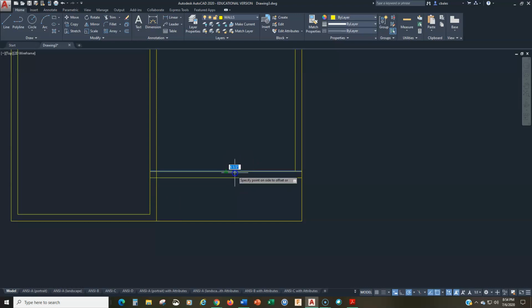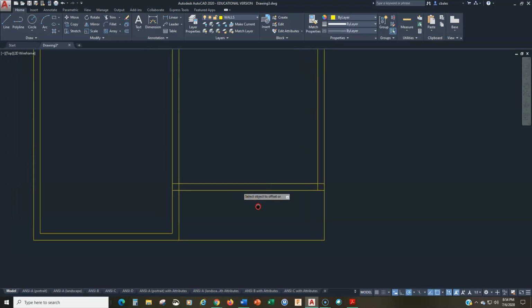Allow me to just talk while I'm doing this drawing. The biggest challenge to me with architectural drawing is just keeping track of the lines and the walls, right? So work along a path. In other words, stick with the front and finish the front detail, and then move on to other sections.